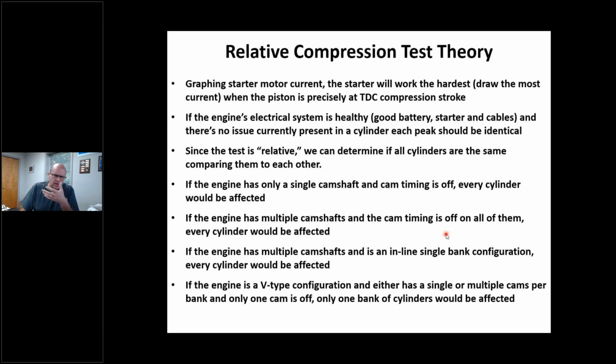So when I talk about relative compression theory, I've got a couple of things here. We're going to graph this current. This is what's different than using a meter. If I have a Fluke meter or something like that, and I go around the battery cable and roll the engine over, my meter is going to average, okay? I've got to graph this to really see. And I can also do a couple other things.